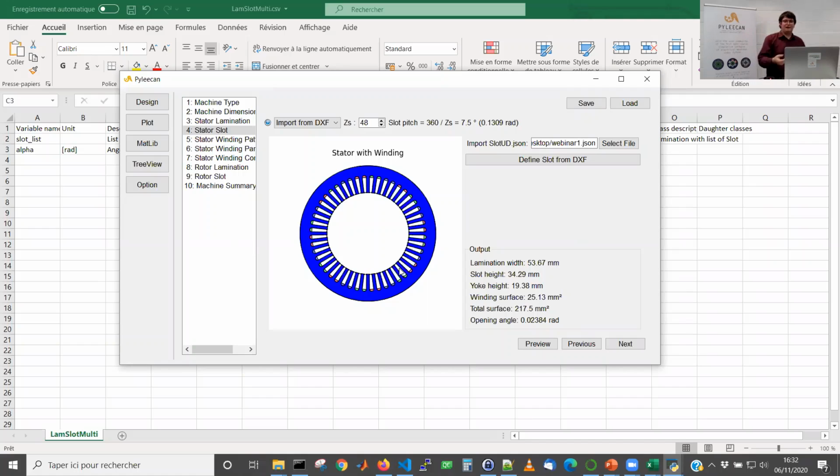And for instance, I can then go even further. I can take my lines, do copy, rotate, translate, and so on. I can completely change it. I can do a parameter sweep around the position of every line. I can do everything I want. It's that flexible, it's that powerful, thanks to the possibility that as long as I have the build geometry and the get surface wind method, I can do whatever I want.